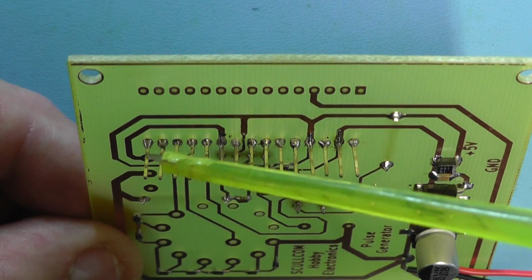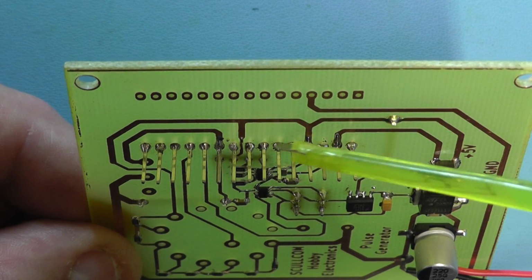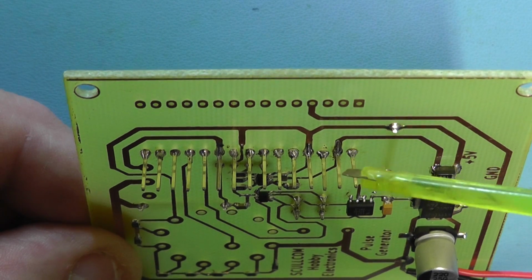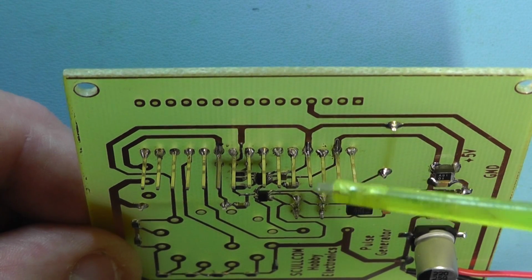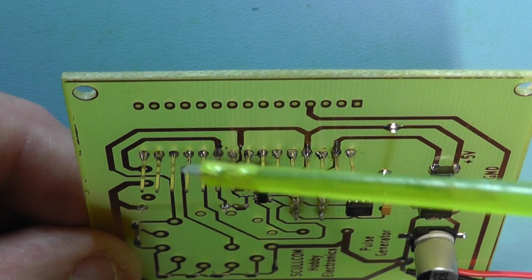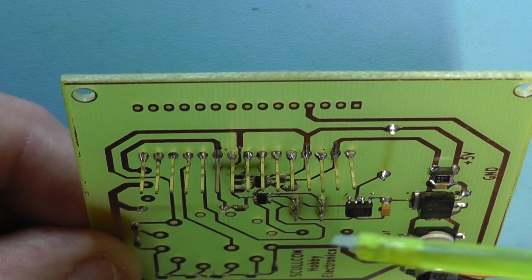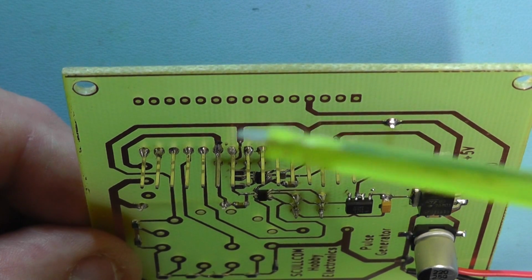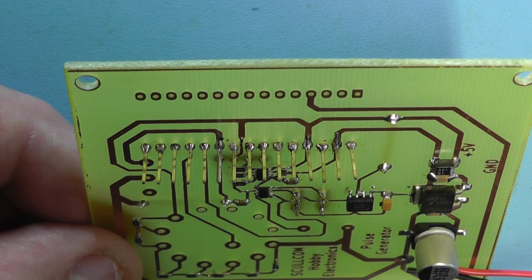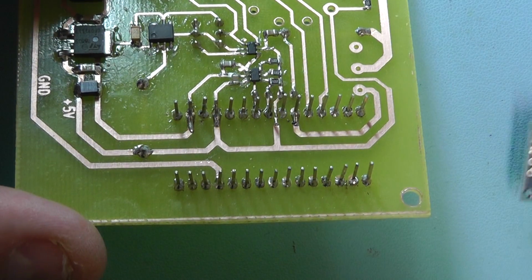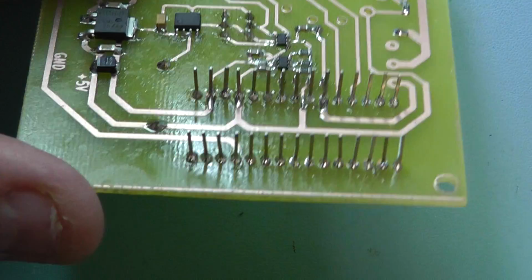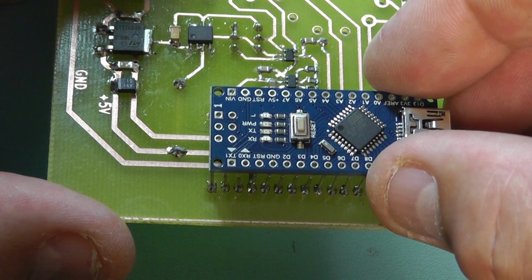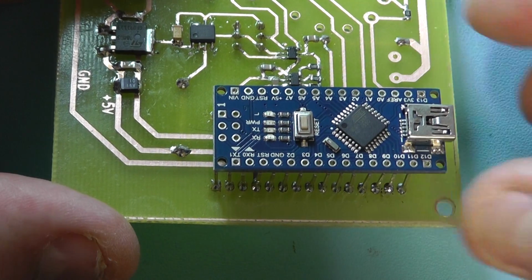Here you see now the pins all soldered in place with the plastic spacer now removed. It's a little bit difficult to remove, I found, so I ended up snipping every couple of pins, and then it pulled off quite easily. So I'm going to do the same for the other side, and those are the pins that we're going to use to mount the Arduino Nano on. There we have all the pins mounted and soldered on the PCB, and the idea then is that the Arduino Nano will then slot on top of that and we can solder that onto there.